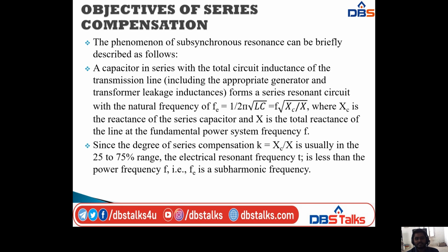A capacitor in series with the total circuit inductance of the transmission line forms a series resonance circuit with the natural frequency Fe equal to 1 by 2 pi root LC, that is equal to F into root of Xc by X, where Xc is the reactance of the series capacitor and X is the total reactance of the line at the fundamental power system frequency F.